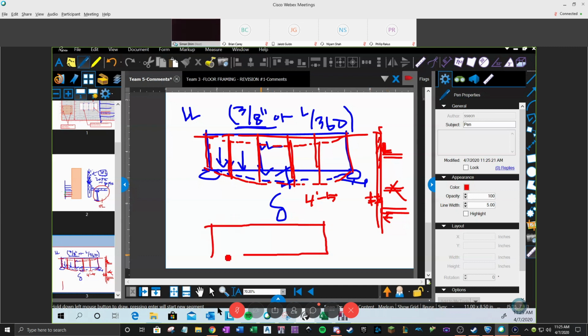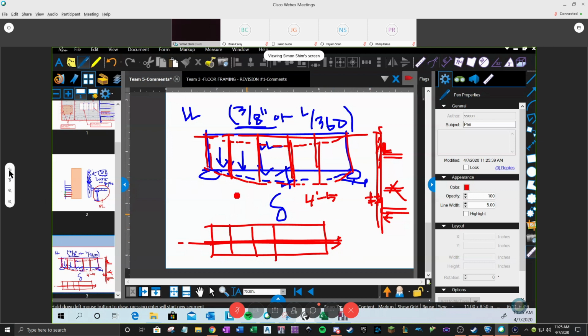When you see the big curtain wall panels, there are horizontal elements that accommodate those vertical movements due to structural deflection, gravity deflection, lateral deflection, and temperature contraction and expansion. Those movements are all accommodated within this stack joint.